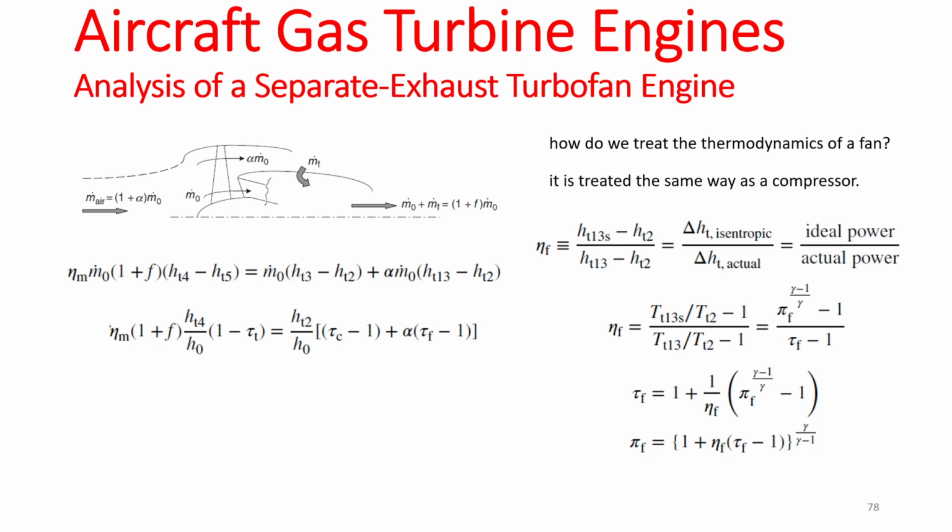So your energy balance is essentially going to be the enthalpy ratio compared to the ambient enthalpy ratio of the turbine exhaust, and the temperature ratios and all of those things. The fan temperature ratio, compressor temperature ratio, which means that we can replace everything.